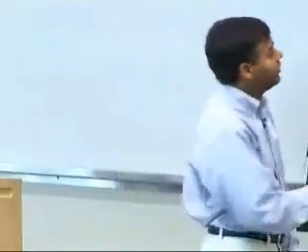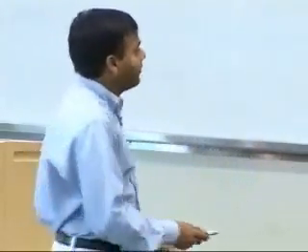Or you could do it using a periodic online self-test, which means that the system is running as it is, and every so often you run a very thorough online self-test, and you find out what's going to happen with these delay shifts in the system. That even provides some cost savings opportunity, because you may not need these sensors and you may not need to pay the power or the area price of doing these sensors and so on, but still you can find delay shifts. So I will get into the details on the next few slides on how one could design some sensors like this, and how one could do this kind of online self-test.